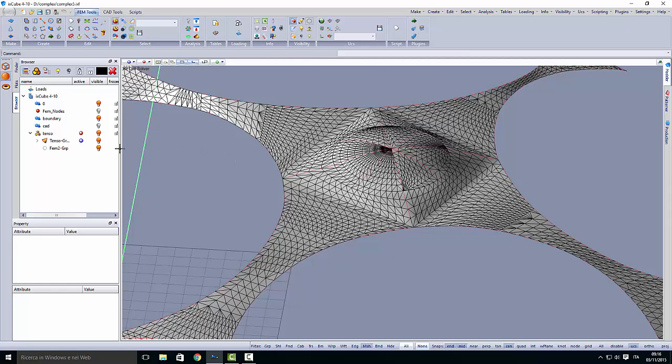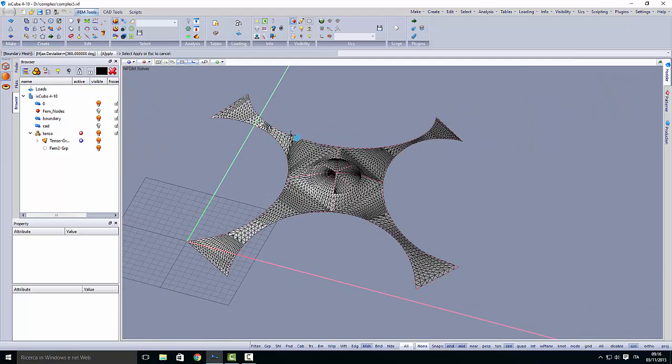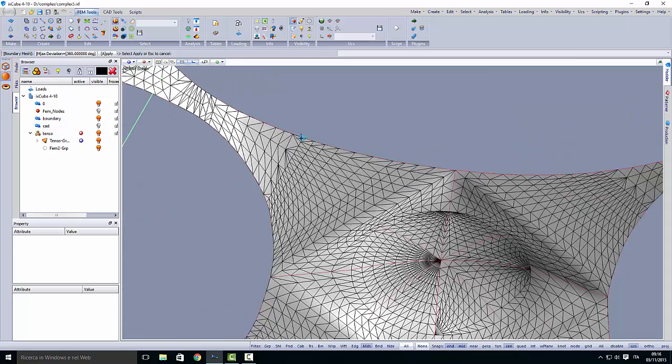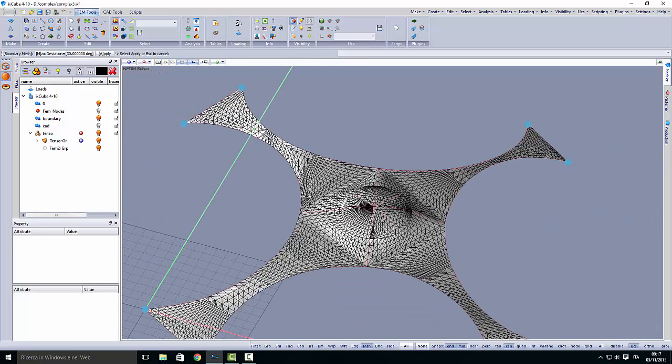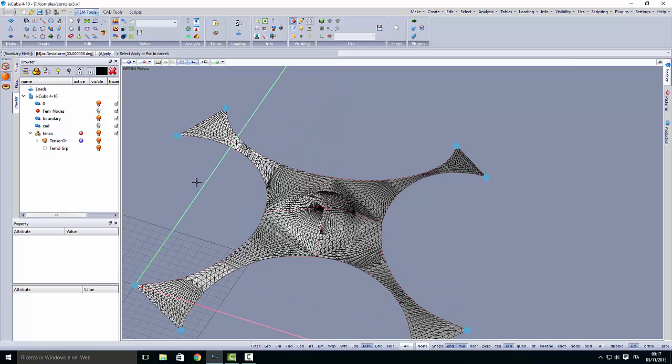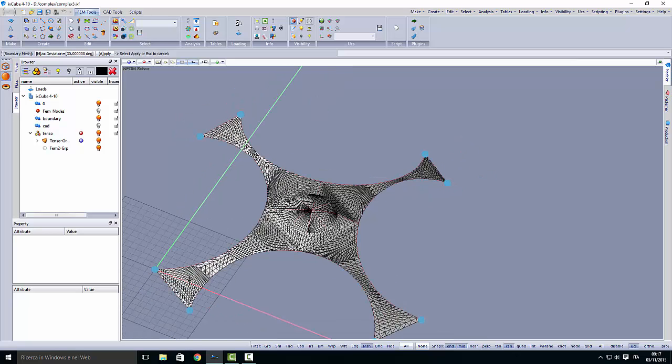The boundary of the mesh, so my tensor group is active. We have this tool here, detect and create a boundary. As soon as we call this tool, we will see a dot. This is the starting point of the boundary. And we have here in the options the deviation angle. Change the deviation angle to a smaller angle. And we can see now that the software has detected the edges, all these points. So in this case, all these will become boundary edges.